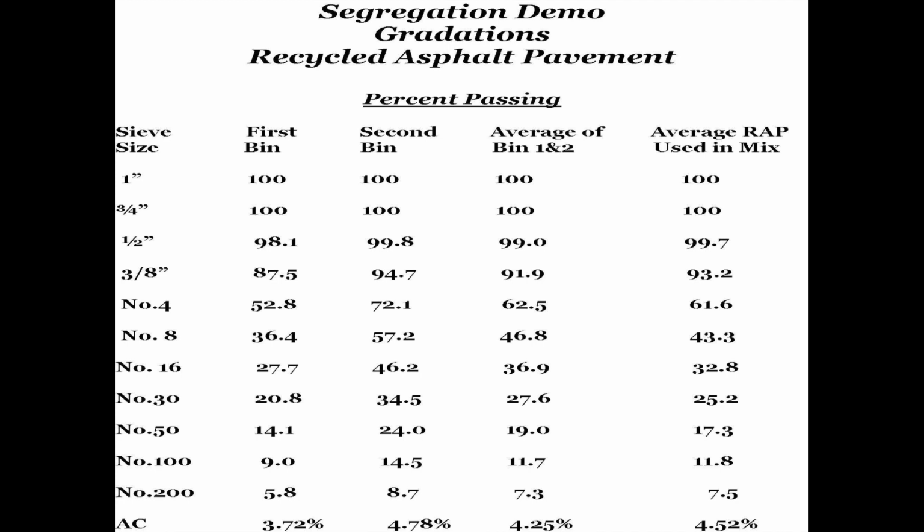And you can see here, I don't know if you can see because I'm probably standing in the way. When you put the averages back together, you come pretty darn close to what we had to start with. So you just think of what you can create by not working a stockpile properly. And I thought doing it with the wrap was a really good illustration because it not only showed you the difference in the particle size distribution, but because you've got all those particles coated and there's much more surface area in those fine particles, it also really affected your binder content.